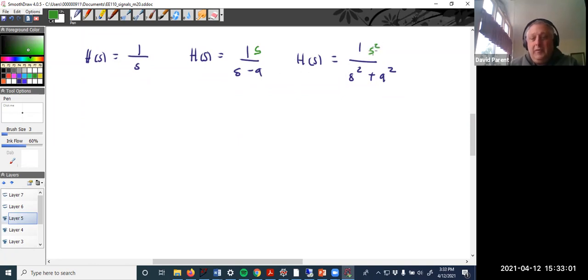In this case, I could put S squared. It doesn't matter. The denominators tell the tale, right? And so this is out of control because the pole at zero acts like an integrator. And so a step response keeps increasing. This acts like exponential increase. So the step response of that is an exponential increasing function. And this has complex, purely imaginary poles. And so the output is a sine wave. And that's why it's out of control, right?